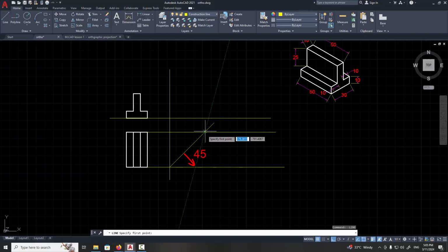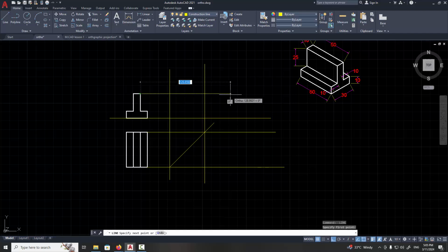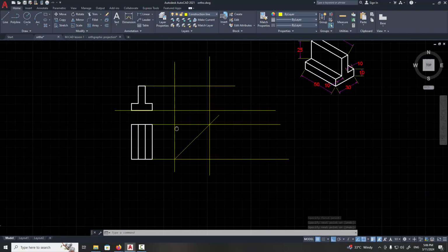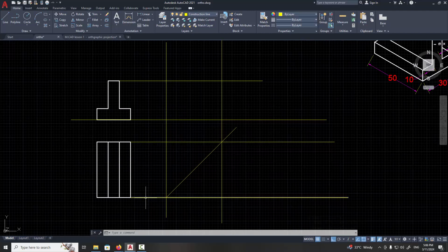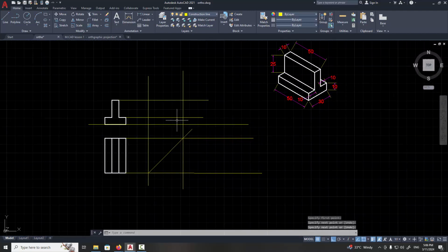This diagonal line will act as a mirror which will reflect the side view and position it next to the front view plane. I have explained in depth the process of projecting the side view in our previous videos, so check it out, as I am moving a bit faster here since this part was explained already. So draw the top line of the side view from the front view, and if we look at the top view, the only part we needed to transfer was the width of the object. Draw a line from the top part of the front view and extend. So we'll be having this section, which is this one, and this section is this one.